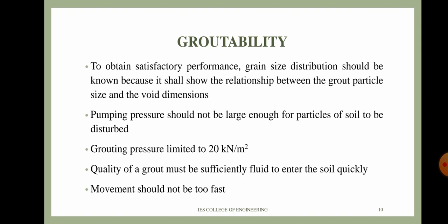Moving on to the groutability. In order to obtain a satisfactory performance of a grout, its grain size distribution should be known because it shows the relationship between the suspended particles and the void dimensions. And best results are obtained when the pumping pressure is not allowed to grow large enough for the particles of soil to be disturbed or moved.